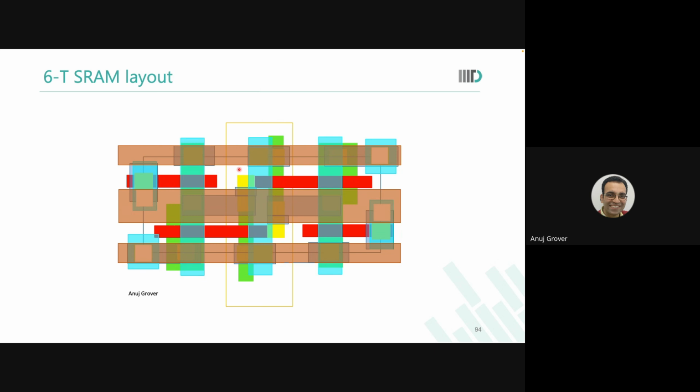Let's say this is that pass gate pull down intersection. Now you said I want to increase the length of my poly a little. So I increase the length, but I do not increase the spacing between poly to poly, poly center to poly center. So what I'm actually doing is violating the poly to contact DRC.